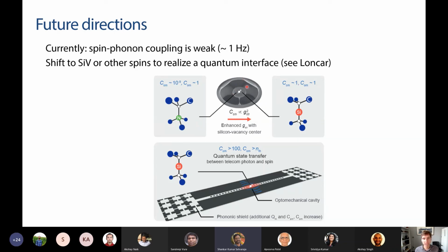Yeah, that's a good point, and I shouldn't have been as confident in saying the fundamental TE. I should have said the fundamental TE or TM mode. I wouldn't say that we have definitively ruled out one versus the other. You are etching the bottom surface, but I'm trying to remember whether we have convinced ourselves that it was the TE or TM. I feel like we've seen high Q modes in each, without one necessarily being much worse or better than the other.